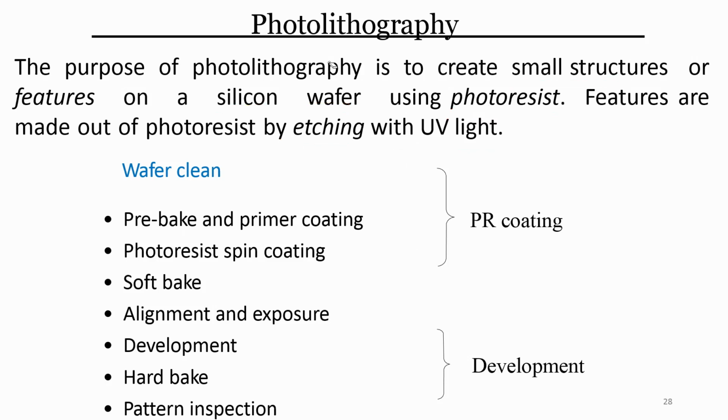Now, when you talk about photolithography, there are several steps involved, and the first among them is wafer cleaning. You cannot, or you should not, start any process in microengineering without cleaning the wafer. Now, cleaning the wafer does not just mean cleaning with DI water, drying with nitrogen, or just pre-baking it. Cleaning of the wafer means, like we have discussed in earlier classes,